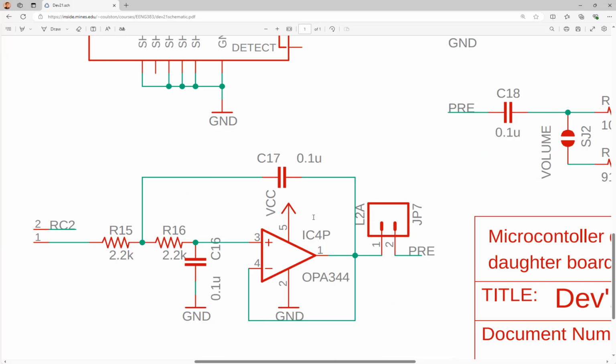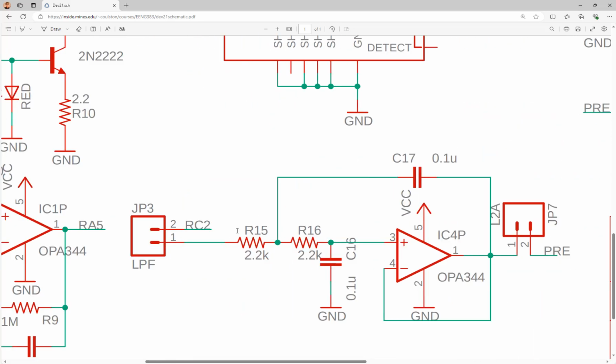You also need an input for the low-pass filter. The low-pass filter is not a signal generator. It filters high frequency signals. So if you look here, the filter has a jumper wire as well. If you do not have the long female to female cable connected from one of the pins, we use RB5, right? Remember? We use RB5 to output the signal to the speaker. If you do not connect RB5 to, for example, here, okay?